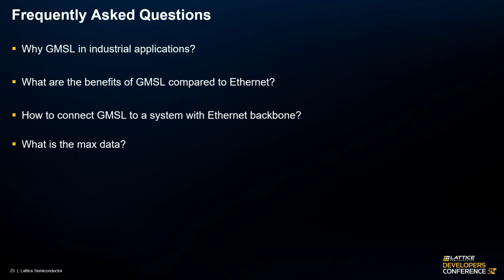Next question, how to connect GMSL to a system with Ethernet backbone? Using an FPGA is a common solution here. A good example is the Holoscan sensor bridge from Lattice, and we have that demo for the LDC this year. This solution is essential for applications with a host platform that doesn't have direct MIPI input.